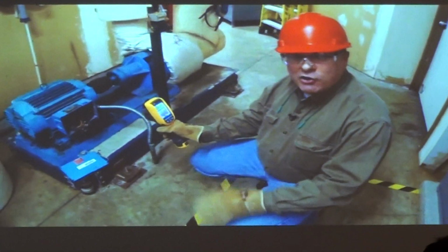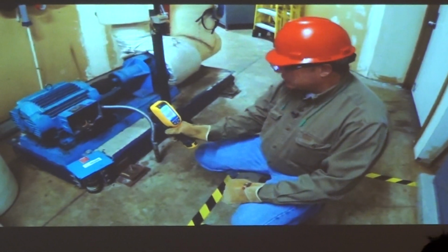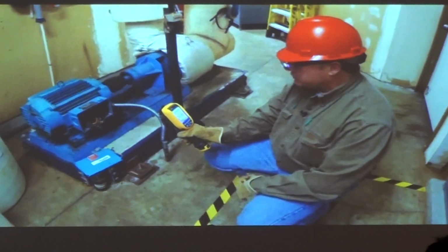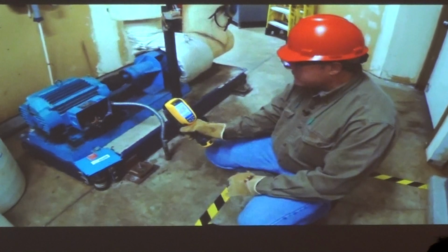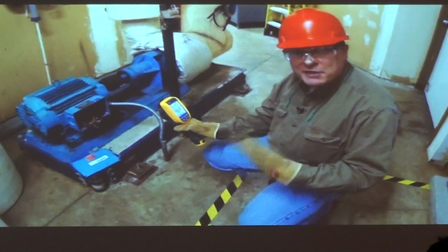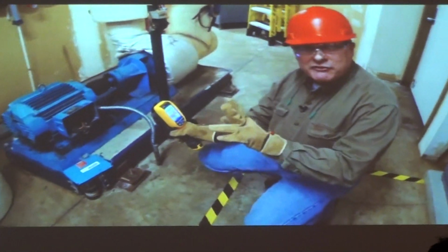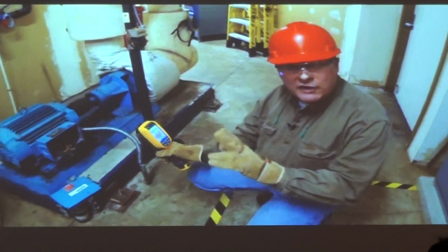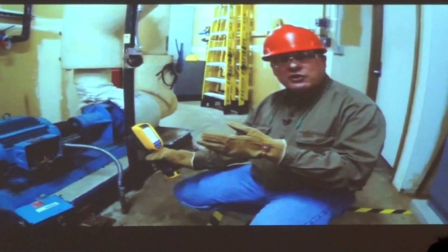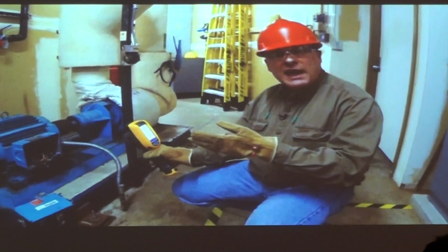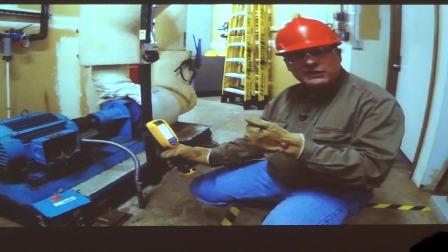And it might not be a whole lot every year, but those kind of connections add up, so definitely take a look at those. Also looking to see if there's any overload situation on any of the lines. I'm not seeing anything there. You know, a single phasing motor may be operational and may be working, but you're going to see two of the phases significantly warmer than the one that was shut out, okay? It'll be a lot cooler, and that motor will start overheating. It will actually draw more power just to try to keep running. So definitely look out for things like that.